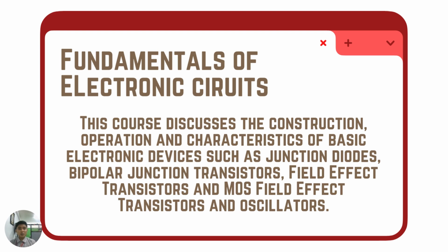So the main difference between the regular FET and the MOSFET is that the MOSFET has a much higher input impedance. Another is that they have high drain resistance due to lower resistance of the channel, and another is that they are easier to manufacture and they support high speed operations compared to regular FETs. So that is why this is one of the most commonly used transistors today, our MOSFET. Okay,